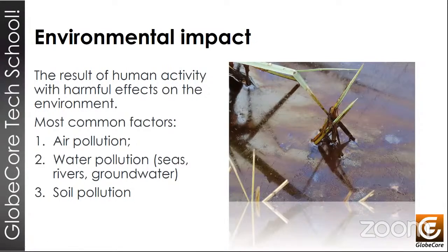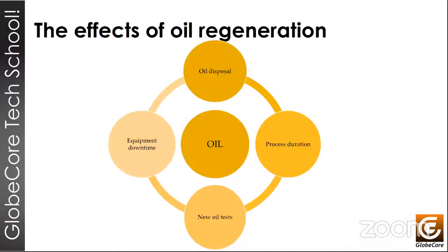Next slide, please. Right, so the regeneration of oil, however, reduces that environmental footprint, and it also offers excellent benefits for the oil-filled equipment in the long run. Regeneration eliminates the consumption of thousands of liters of oil, and the time costs are also reduced because it's possible to regenerate the oil online. It means that we don't have to turn off the transformer to regenerate the oil. Of course, this involves some safety precautions, but it's entirely possible.